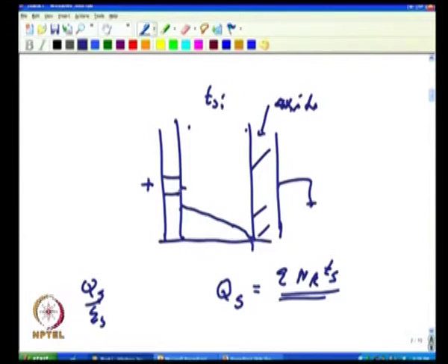Now, whatever electric field has increased here, everywhere it will increase, because there is no charge there, or whatever field line originates from there terminates there. And once it reaches here, there are no charges in the oxide. So, what will happen? It will cross the oxide, but the electric field here in the oxide will be higher, like the electric field here.